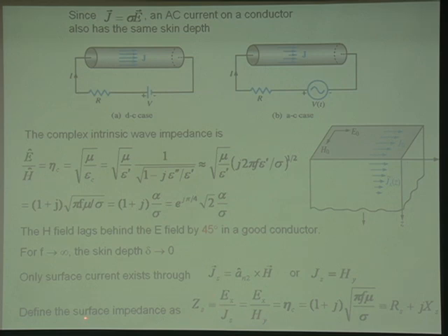We define it to be the surface impedance of this wave when it is just incident on this piece of conductor. But this Js has been calculated to be equal to Hy, so this surface impedance is also equal to Ex over Js. And this basically is an expression equal to eta c. So eta c is the surface impedance of a piece of metal.